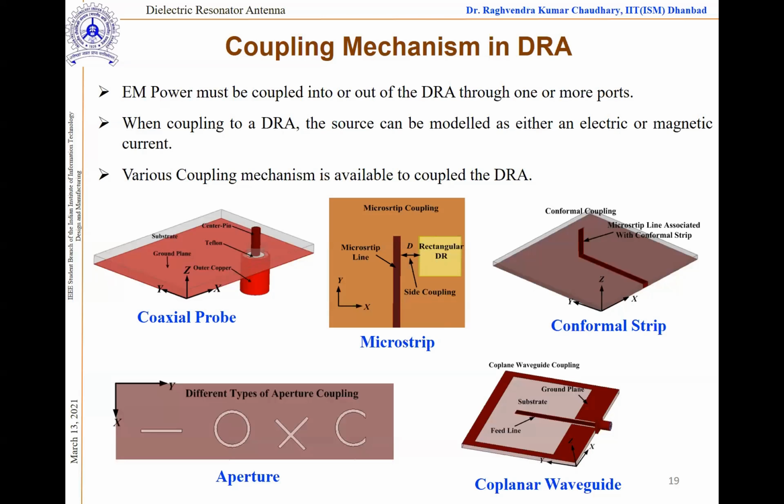If you recall your UG days, you performed experiments on a microwave bench, and that bench was actually TE10 mode, which is a fundamental mode, and we ran all the experiments over that mode only. Have you tried to open the waveguide and understand how this mode was excited?